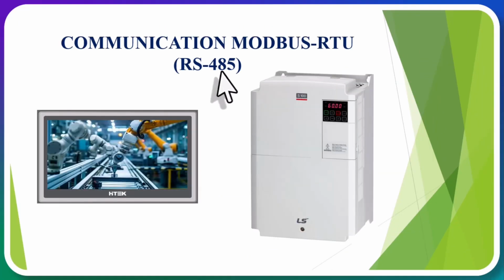Specifically, today we want to connect the 100 inverter to an HMI using the Modbus-RTU protocol over RS-485, and in this way send the frequency value to the inverter and perform start and stop operations through the network and the HMI.